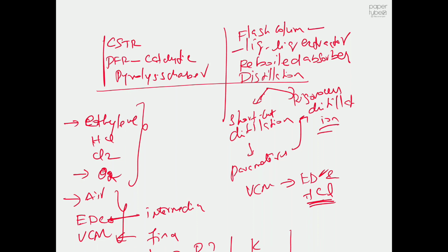the temperature in the liquid extractor, what's the temperature and the pressure that we need to maintain in the reboiled absorber. Regarding the distillation column, I already said what should be the process conditions, so where we can perform this particular unit operation in a more economical way, yeah? Like so that we should maintain the reboiler temperature less than, I think, 186 degrees centigrade.